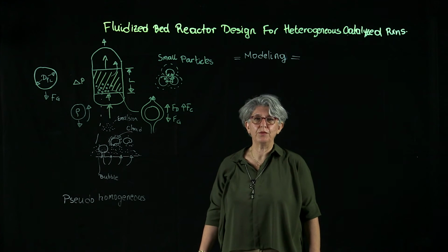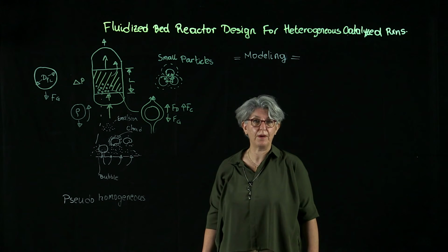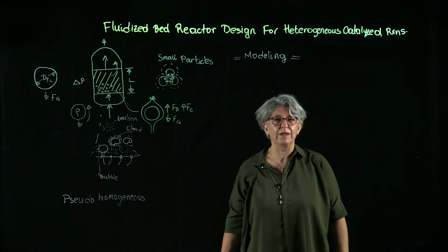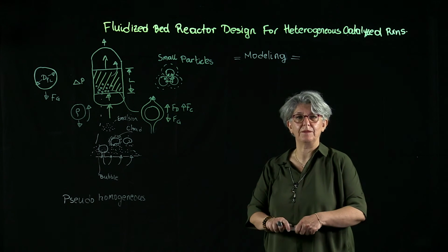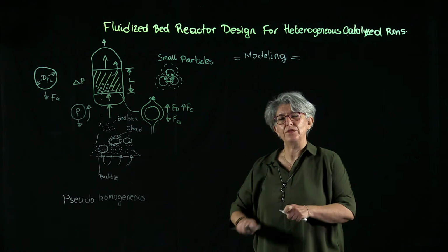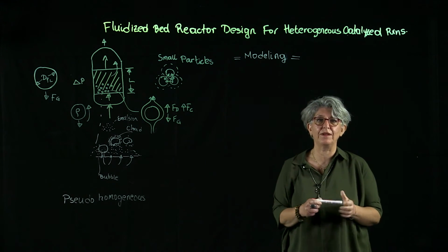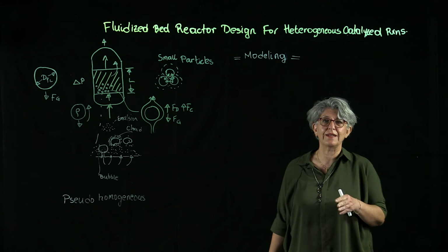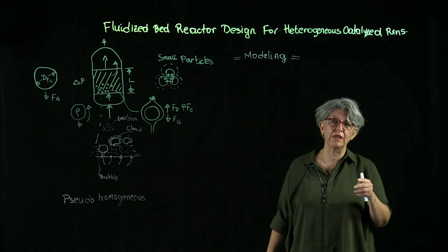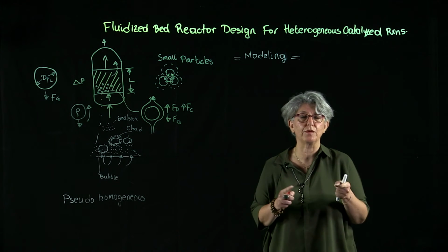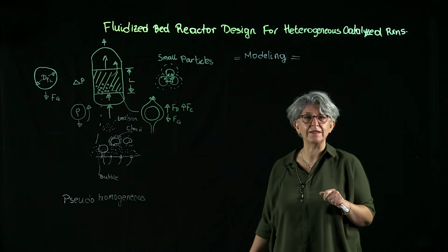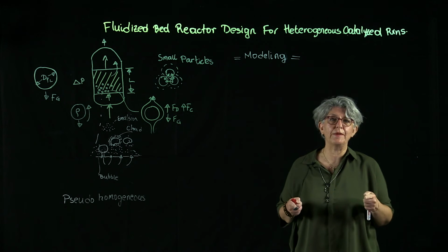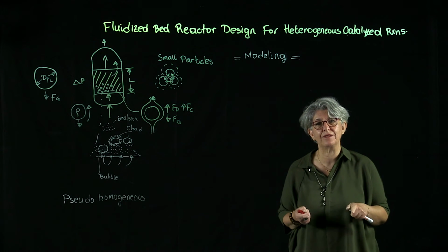In this part, we are going to discuss an industrial problem of fluid catalytic cracking reactors that are very common in petroleum refineries. Now, fluidized catalytic cracking reactions take place on zeolite catalysts, and the reactions are highly endothermic. The cracking reaction, breaking carbon-carbon bond and substituting the empty bond with a double bond or with a hydrogen atom coming from cracked product or steam available in the reactor, is highly endothermic.